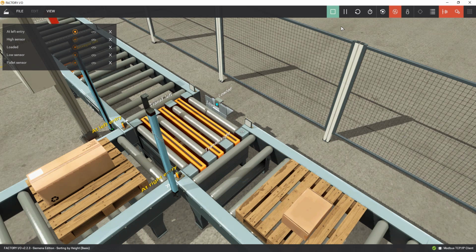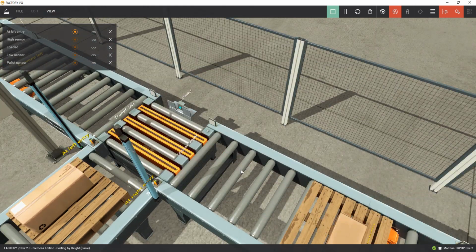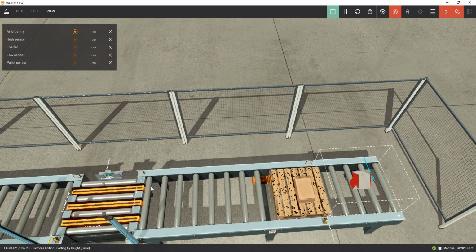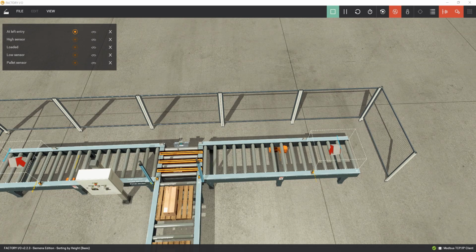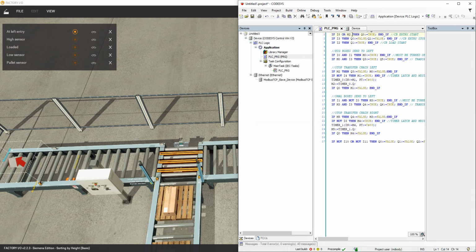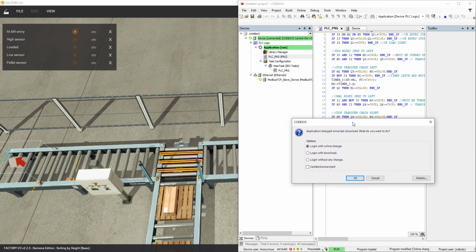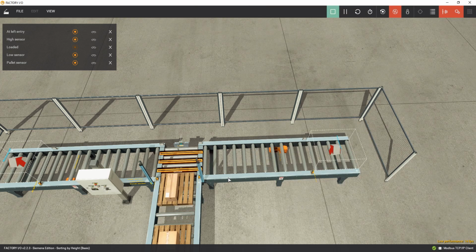Right, then the signal here must turn on the conveyor belt. It's not doing that. The signal over there must turn on the conveyor belt. Let's just fix that. The signal at M5, or, remember the OR, M5. When M5, then M3 turns off. Perfect. Let's see. You see, by default, product starts to come in.